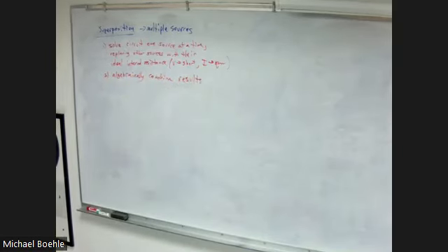Algebraically means what? You pay attention to polarity if it's voltage, direction if it's current. And if they're both the same, you add them. And if they're opposite, you take the difference. Or you make an assumption about which direction or polarity you have. And if it contributes to that polarity, it's positive. If it's the opposite, it's negative. Then you find all the results. All right.